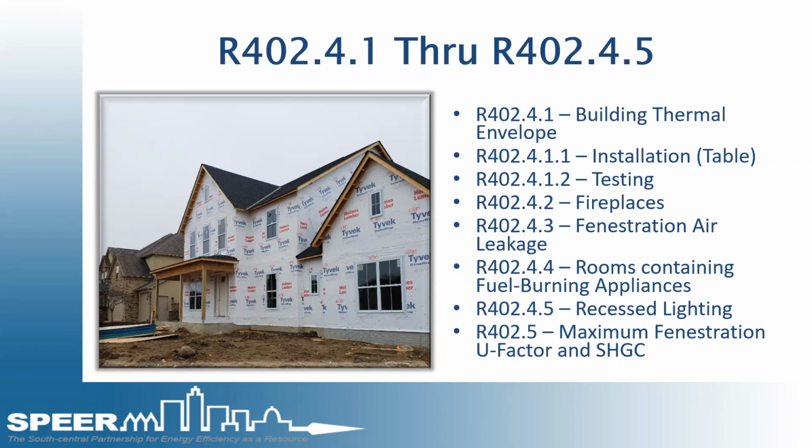Rooms containing fuel-burning appliances, that's anytime you have a gas water heater or a gas furnace inside the conditioned space, need to be handled properly in specific climate zones. And then recessed lighting: how are they sealed, how do you have to address those, and how they need to be insulated and be IC/AT rated, so their insulation contact must be airtight.